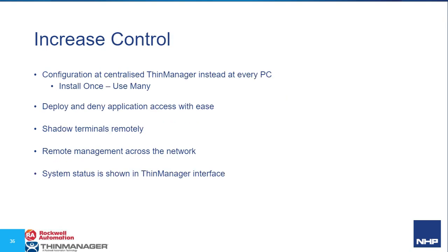Control. I'm enabling configuration of everything from my centralized desktop and from my office. So I can install ThinManager, I can install my applications once on servers and use them as many times as I need. I deploy those applications out to the thin clients, to people who are authorized to see them. I do not typically deploy a full desktop. We don't need a start menu. We don't need the operators interacting with an operating system. We just need them in front of the HMI.